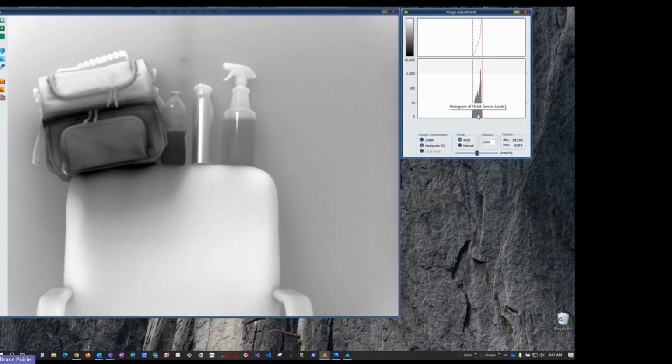What histogram does is it adjusts the slope of the transfer function so that you get higher gains where you have the most pixels. If you don't have any pixels at a certain level, they don't count for anything and they don't apply to the histogram. If you have lots of pixels at a certain level, then we apply more gain to that level.